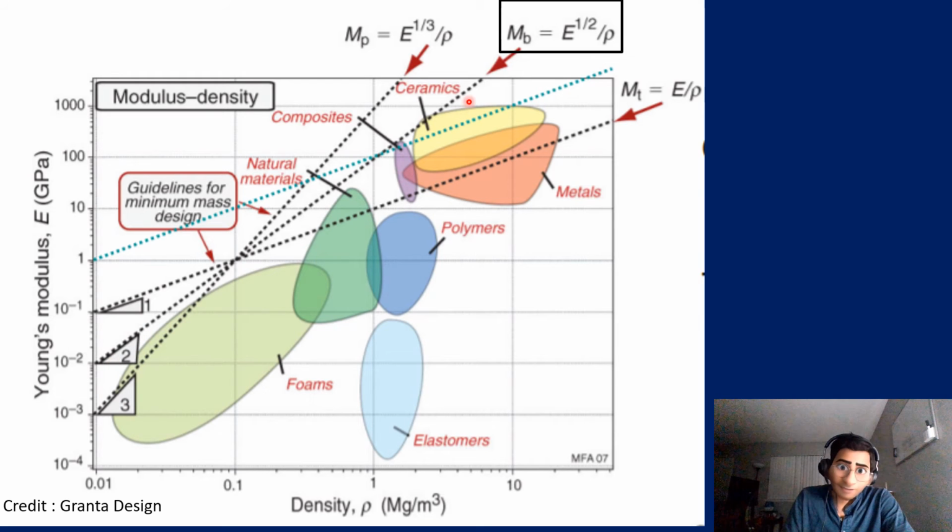And if you see right now, since our objective changed from just elasticity, now we are concerned more about weight and mass. So some other materials seem closer to metal now, like foams and particularly these natural materials, like wood and all, which, if I make this slope go down, this slope will hit this particular section before metals because metals are highly dense. But it depends upon what you are trying to maximize and minimize.